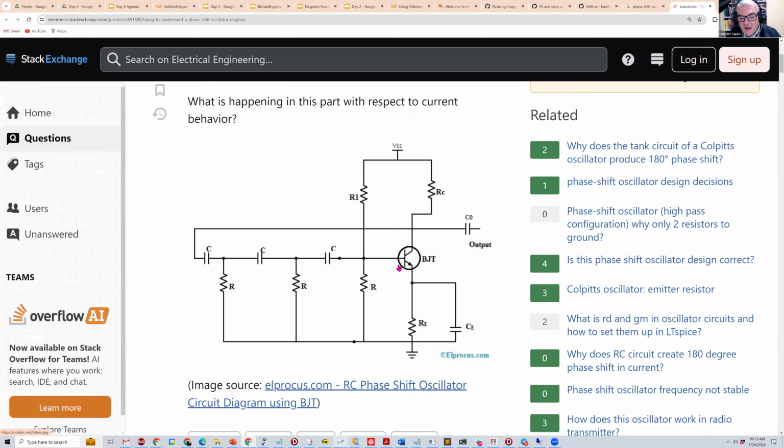They look like this. And you may think this is nothing like the biochemical network you just showed us. But actually, it's very, very similar. There's the negative feedback unit, which in this case is a transistor. And the three capacitors are the three species in the network, and they act as the phase shifters. So the signal goes all the way through the capacitors and into the base of the transistor, and that's the loop. So it's actually exactly the same thing as our biochemical oscillator. And all phase shift oscillators are like this.